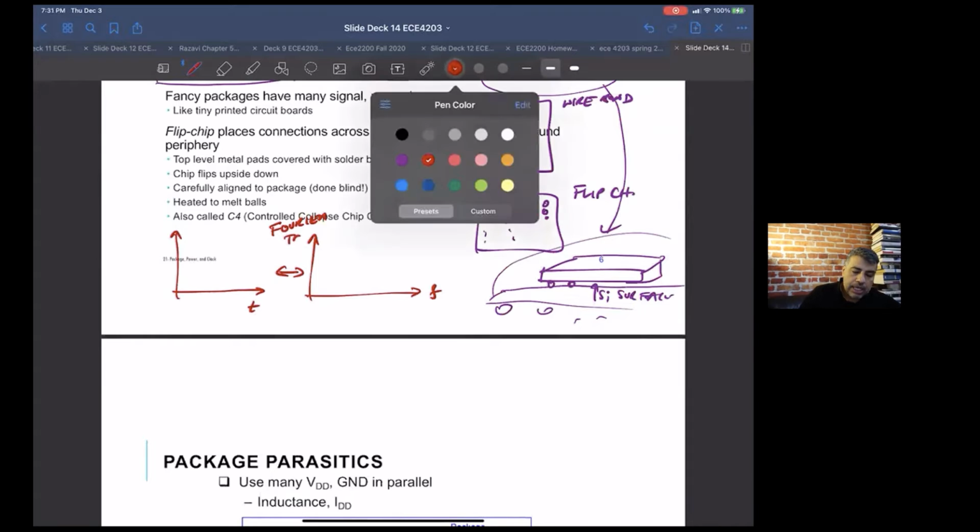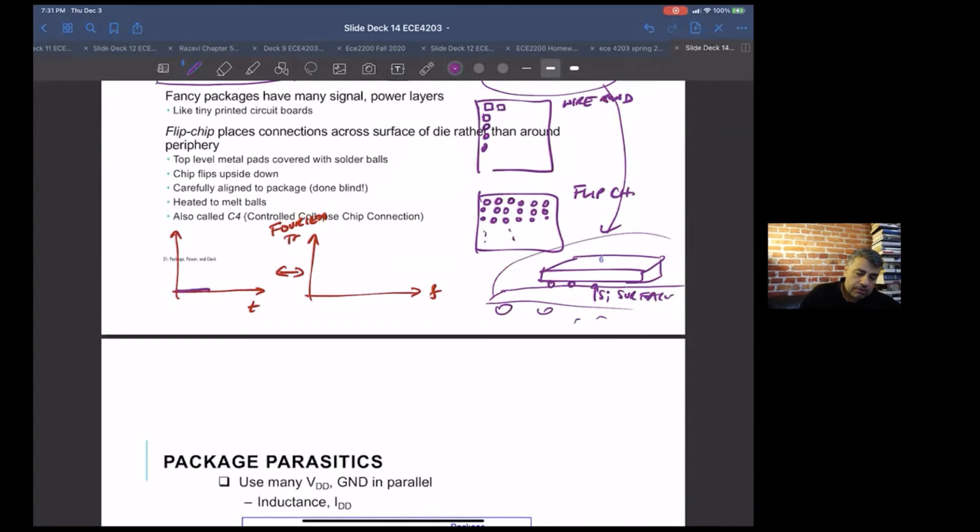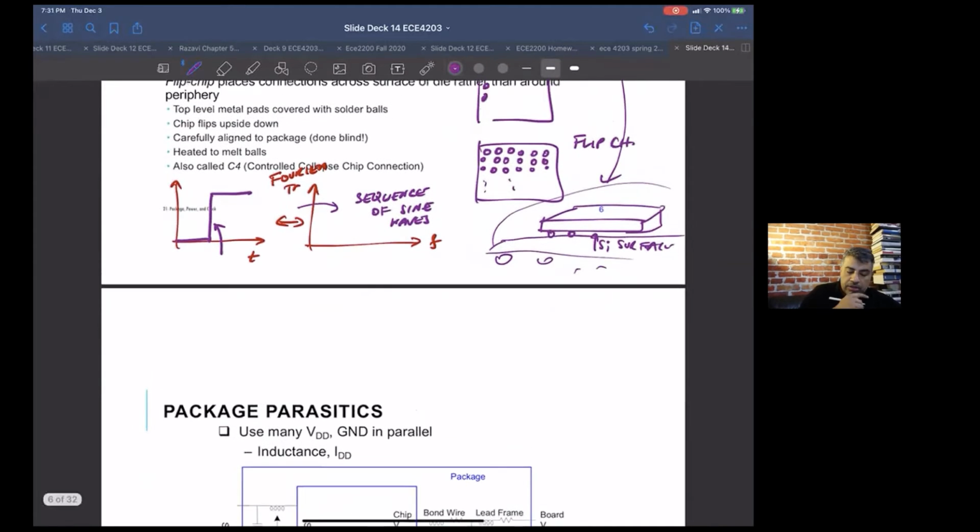And so let's say you have something with a square wave with a fast rising edge. So this rising edge, you would do a Fourier transform of this thing, and you end up with a Fourier sequence of sine waves. I can't draw them, but you end up with a bunch of sine waves. So this is where digital and analog start meeting up.